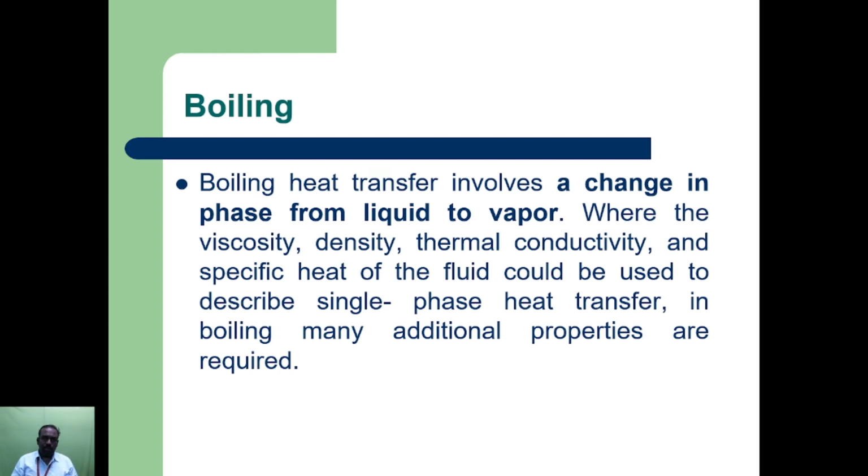Now we are going to study boiling heat transfer, the transition from one phase to another. Boiling heat transfer involves changes of phase from liquid state to vapor state. Viscosity, density, thermal conductivity and specific heat of the fluid are important parameters used to describe single-phase heat transfer. In boiling, additional properties are required.